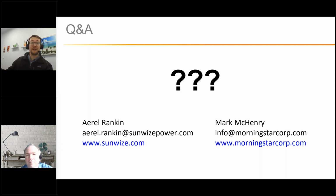So on the extreme end of the case, I can recall a couple projects that we've done in like Saskatoon, Canada, for instance. You can have a multiplier to be able to have an amount of energy storage at -40 F that you would have at ambient can be as high as a 16x multiplier. So eminently doable, but it can be a very large multiplier at those extreme temperatures.